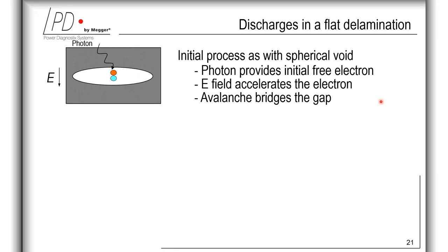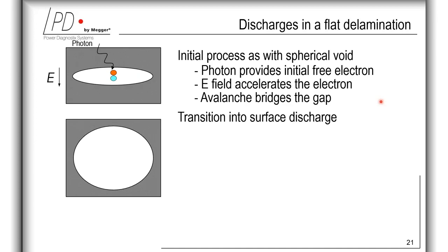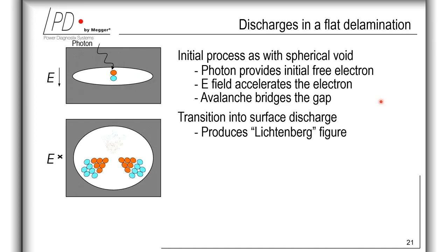Such embedded air pockets are the consequence of various degradation processes of technical insulation systems, such as delamination within mica layers, or gas-filled pockets between paper layers of transformers, or can also be delamination in cable accessories. The figures here show such a delamination in a side view and in a top view.